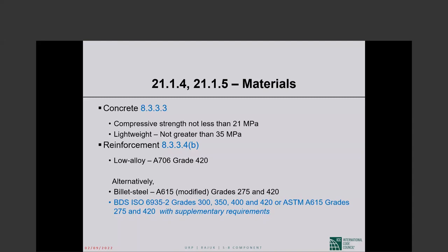That limit used to be a bit lower, and has been brought up in view of more test results being available. It is quite conceivable that with more test results coming, that limit will be adjusted. But up until now, I mean 2022, that limit has held at 35 MPa. That hasn't changed even in 318-19.